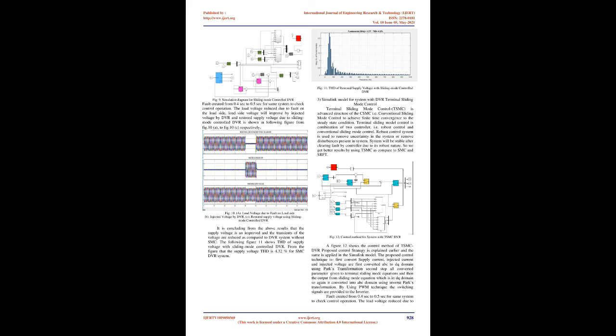Fig. 8, THD of restored supply voltage. From figure 7, the load voltage THD is 36.37% during the sag period, and figure 8 shows the THD of restored supply voltage without SMC DVR, reduced to 5.13%.